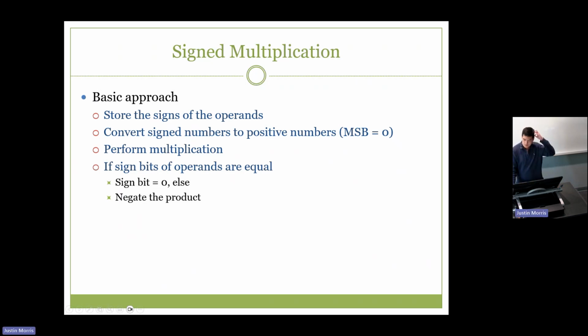So just like we could reuse the adder hardware to do subtraction by just adding a little bit of extra circuits to our hardware, we can do the same thing to do signed multiplication. So for signed multiplication, we're just adding a little bit of pre-processing to convert everything to positive and making sure that we remember what the signs were. And then a little bit of processing at the end. Check, does it need to be negated? If it does need to be negated, negate it. But in the middle, the multiplication, the actual big step for the algorithm, it's using the same algorithm, right? So it can reuse.